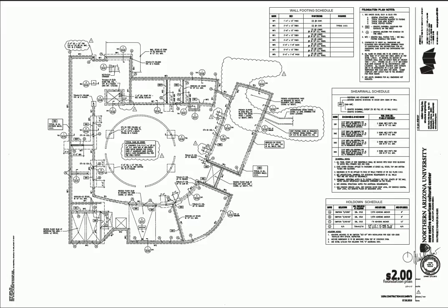So I open this one up and I can see a floor plan. We can see down here this is a foundation plan. The plans tend to go in sequence from the bottom up. What I find very curious on this drawing is that there are no real dimensions showing me how to lay out the whole building. So right now I'm a little confused. I don't know how big this building is. I don't know really what's going on. I can see that it's probably a concrete foundation, but beyond that, it doesn't make a lot of sense to me quite yet. So I'm going to keep digging.